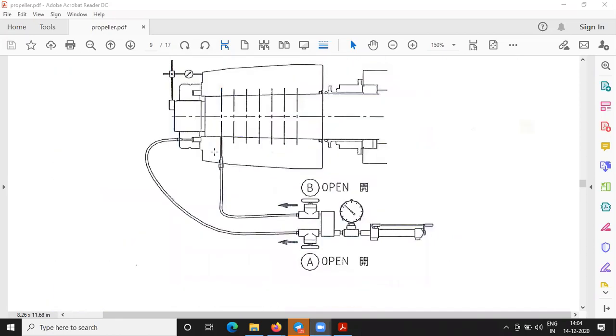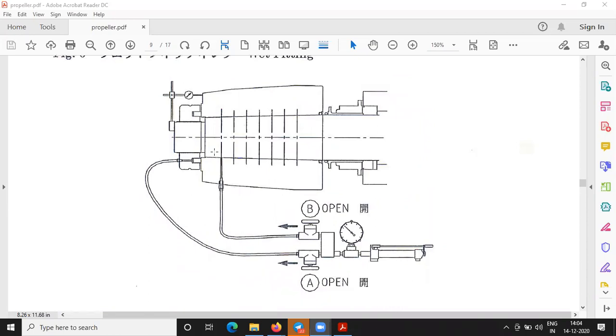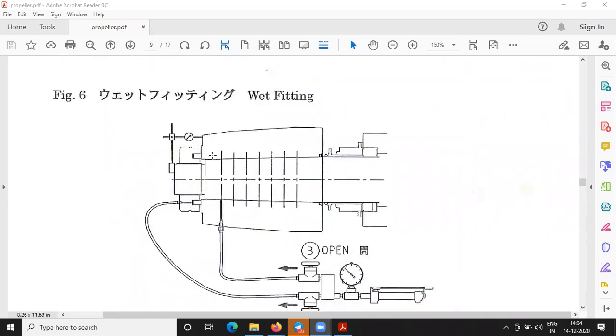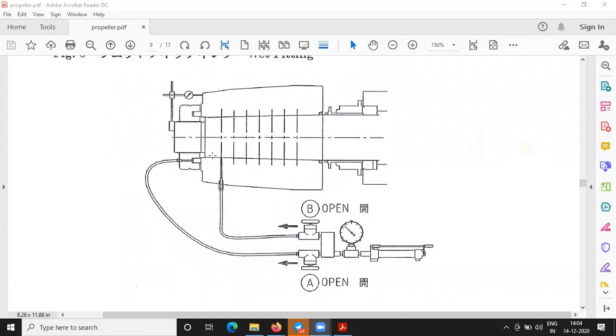Sir, one thing I wanted to ask, this actual push-up distance, what is its significance? We can say that whenever we remove and fit the propeller, the actual push-up distance will always remain the same in any temperature conditions. That's why we need the standard point. Yes, sir. You can say that the actual push-up distance remains the same in any climatic conditions or the temperatures basically we are seeing. But what happens? The theoretical push-up distance changes, but the actual push-up distance is what matters.